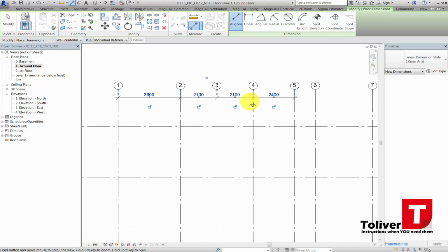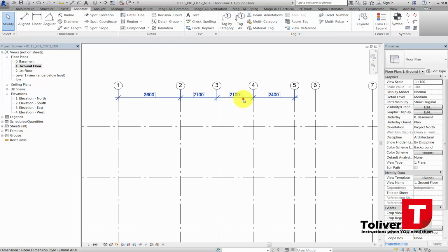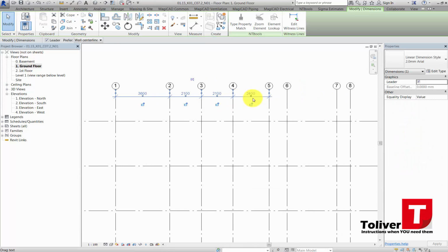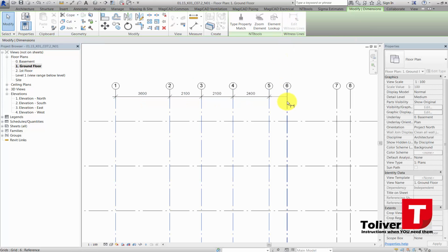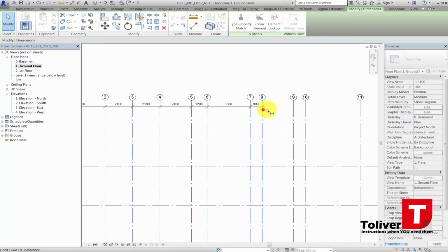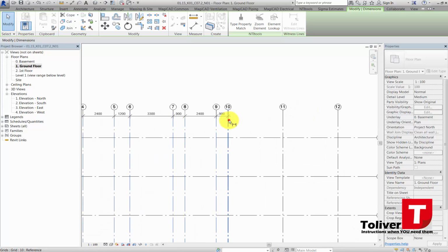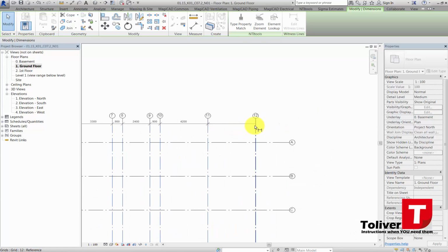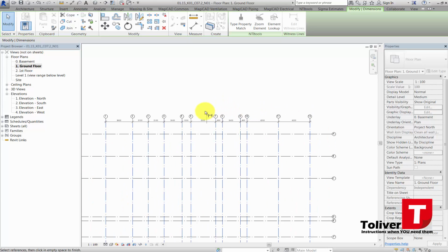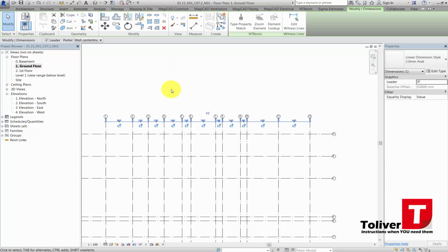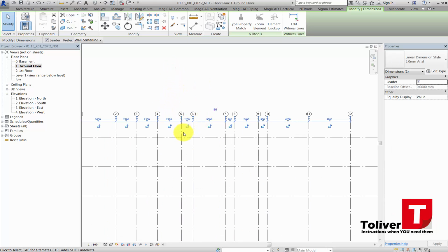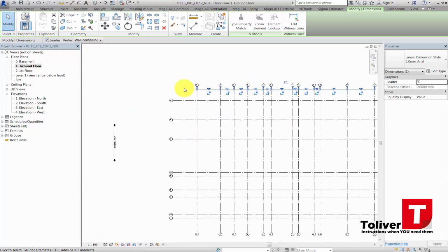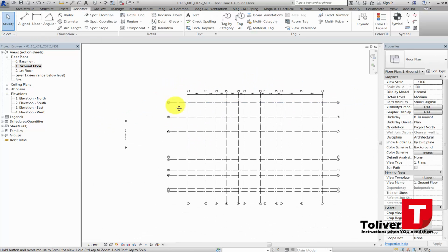And that's an accident, and if that happens, don't start a new line. Don't go up and annotate and do a line and then continue from here. Choose the one that's already existing and go up and say edit witness line and then continue. The shortcut for that was EV. Something like this. And once you edit something, don't press escape when you're done. You have to click somewhere else, because if you press escape, it'll just say okay, he didn't want that, and then cancel the changes that you had done.